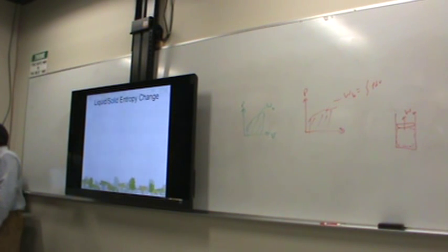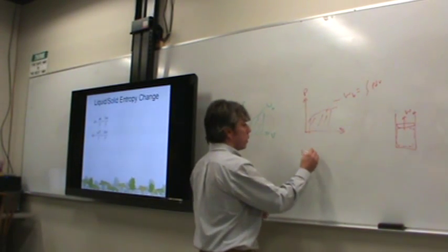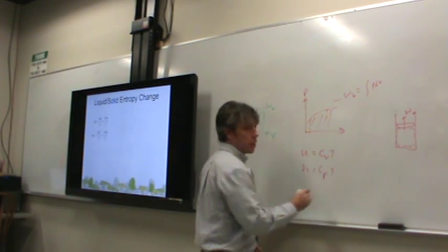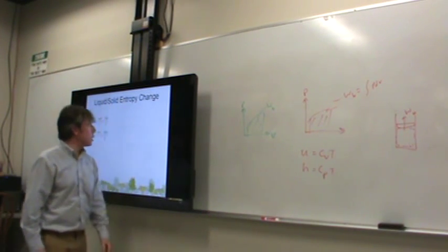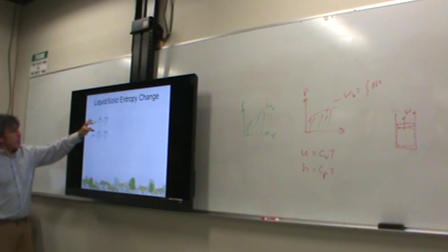Now, we will be very interested in entropy changes of solids and liquids. Well, for a solid or liquid, we could take this first equation, which involves internal energy, pressure, volume, and temperature, and we can make some substitutions, because remember, I had you guys write U equals CvT and H equals CpT in various forms, so that you would relate Cp to H and Cv to U. Okay? Well, dU could be written as C dT.